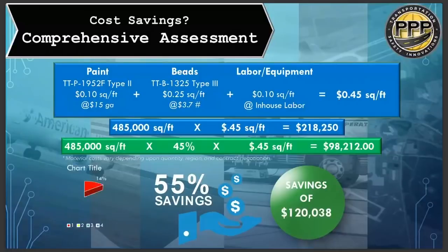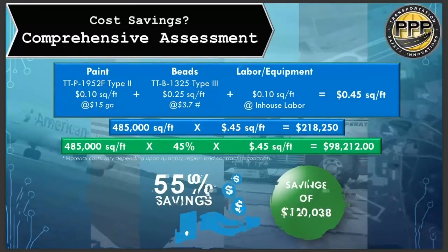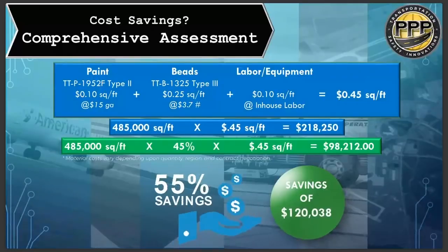Hey, one thing I wanted to add to that, Greg. I agree with everything you said. In the airfield world, we don't repave every 3 years for some roads. What we find is constant, usually annual painting right before Part 139 inspections. We get buildup, and I'd say 50% of the airports that I've consulted with in the last 10 years have to implement a removal program before they can even enjoy this kind of thing.